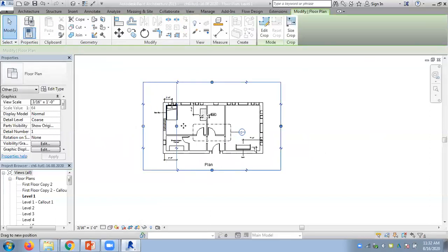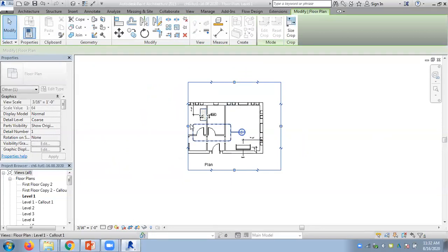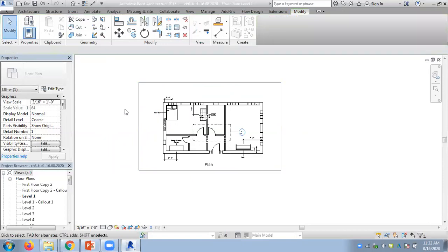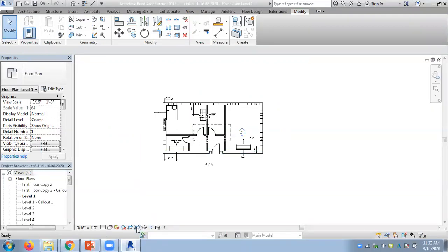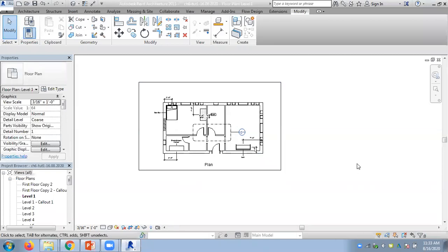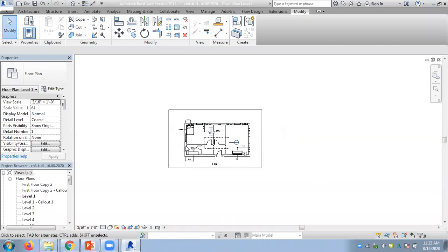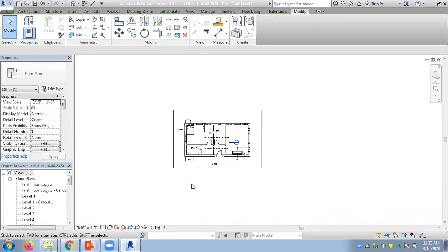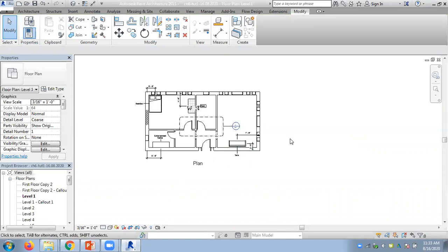So if you want not to show these things in the drawing sheet, just crop it. So the entire plan view is now cropped. So if something is drawn here, it will not be shown in the drawing sheet. So remember that you can hide the things. Normally it's hidden. This way you can unhide the things and see whether the boundary is covering your drawing. The boundary can always be extended to this area and you can draw something here. Then that can be taken to the drawing sheet. So there's a tool like that. We will show it later how we can apply it.